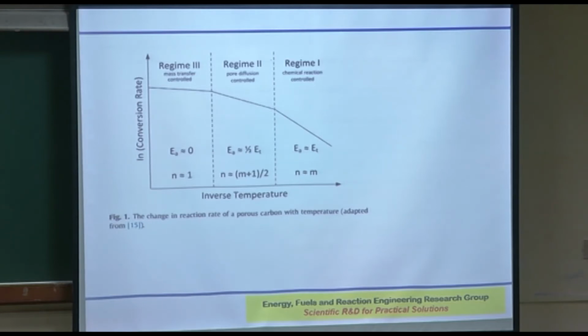It means when the reactant has been able to come to the surface, overcoming the barrier of the surrounding gases, it then has to enter the pore, because the pores are all tiny. And that's where Knudsen diffusion will be controlling, because the size of the pores in some cases is very, very small compared to the mean free path of those gaseous reactant molecules.